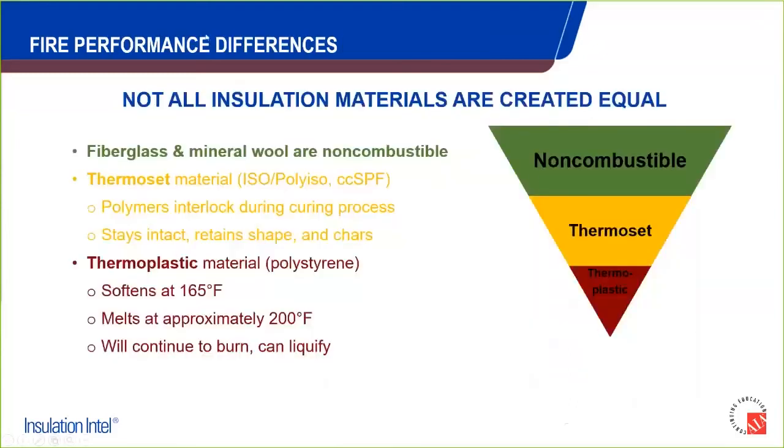So these are really the three primary product categories or buckets which most of these insulations fall into. The safest is the completely non-combustible, and this would not require NFPA 285 testing: fiberglass or mineral wool products. Fiberglass itself melts at about 1200 degrees, mineral wool at 2100 degrees, plus or minus 100 degrees there. And that product is very safe and doesn't trigger the requirement.